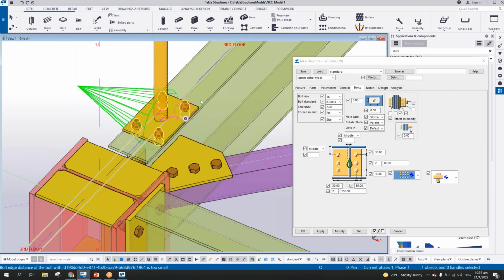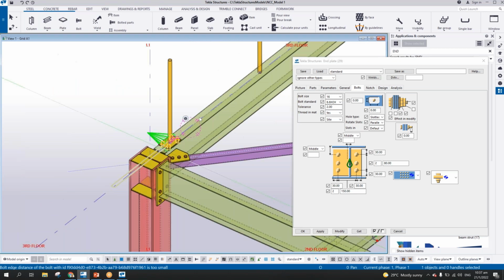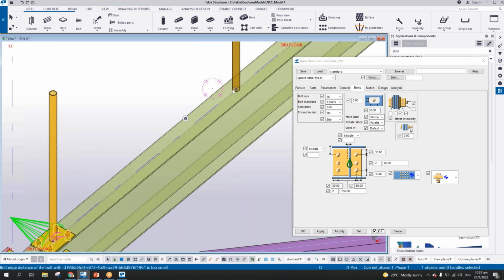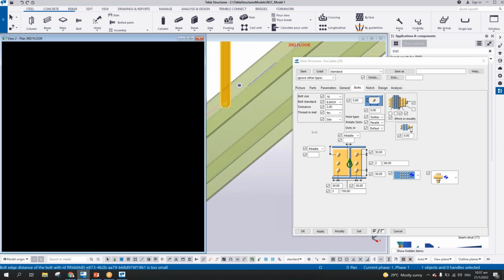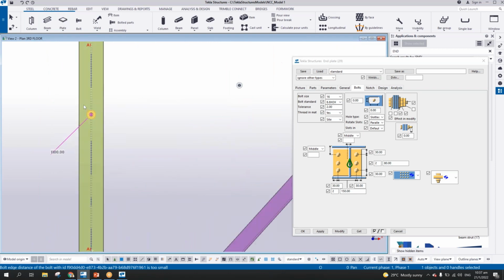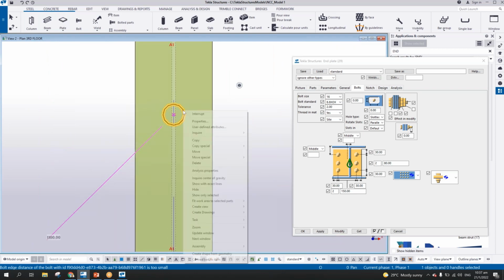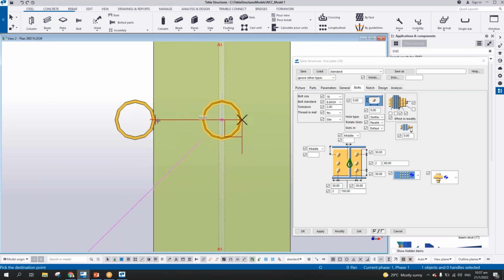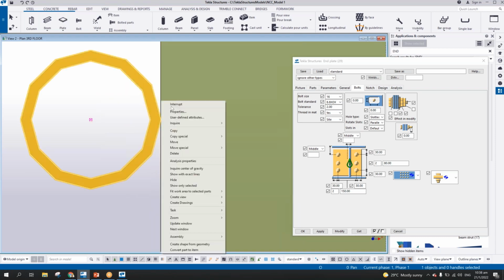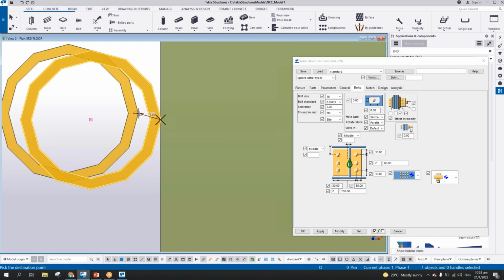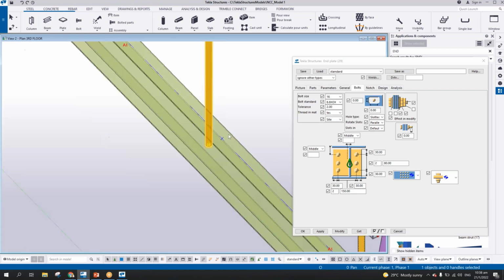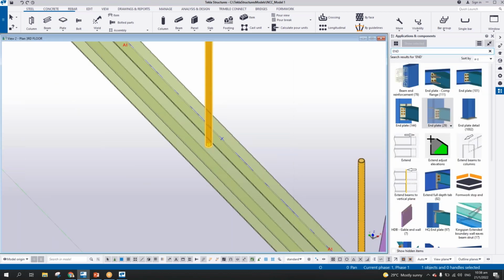Okay, right? So now, what if the stanchion is connected on the web? So what happens is from here, you go to the next tab, to the top view here. So this one, you can just simply move, okay? Move this one, this to this. So let's say this point, and then move another 10 millimeter, like that. So in case this one is connected to the web, then you can now use the stanchion connection.